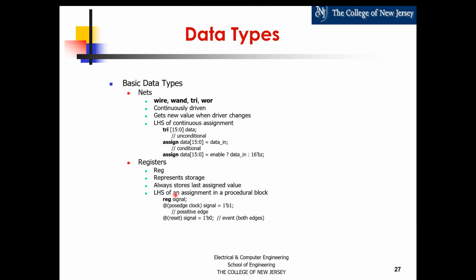We have that ability to make that assertion because this is a hardware description language. If we don't specify something like posedge and we say at reset, then this is sensitive to both edges. And that's the most sensitivity that you can have. You can only be sensitive to the events of edges because this is for digital systems.